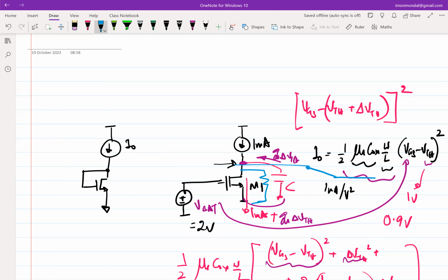Now we are trying to say that I want the current to be the independent variable. If the current is the independent variable, then obviously I cannot make the battery, the VGS, another independent variable. Then there will be a conflict. Essentially, two current sources will be fighting each other. This battery is trying to fix a current here, and this current source is trying to force another current into the MOSFET, and there is a conflict.